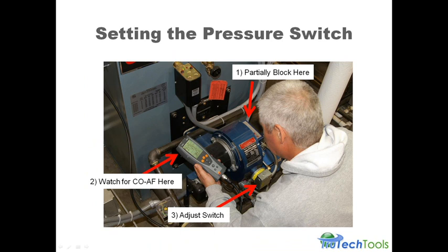Now in this case, this is a commercial application. I'd set it to 400 ppm because it's for the ANSI standard. And in a commercial application, hopefully you're going to have somebody that's testing the appliance more than yearly, because you have a service contract on this or whatever. Somebody's doing a monthly test on this appliance. And when we have that kind of testing being done, we can definitely tighten up that excess air reading a little bit more and do it safely.